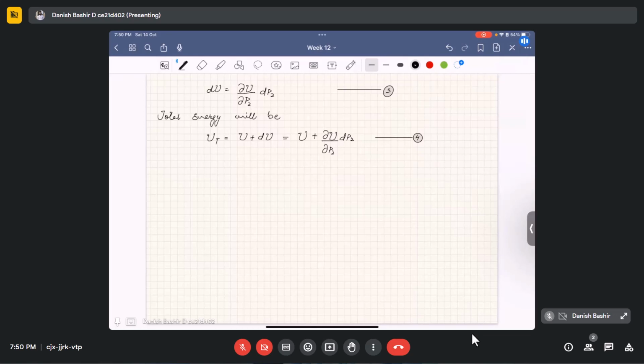That is P1, another load P2 plus dP2, and another load P3. The total strain energy stored in our beam should be the same, assuming linear elastic behavior, after dP2 is added. Okay, this is clear.